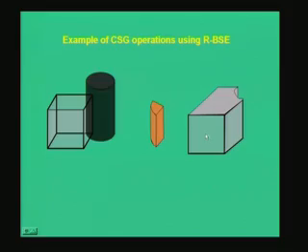So, you can see that again it is a two level decomposition or construction of the CSG. At the lower level you will have an intersection operation and then a difference operation which will create that final structure. And of course, at the lower level, as the leaves of the tree for the CSG, you will have the cylinder, you will have two different cubes, or one cube, one rectangular parallelepiped, and the intersection operation creates the structure in the middle, and that is again used by the last operation to create the final structure at the root.